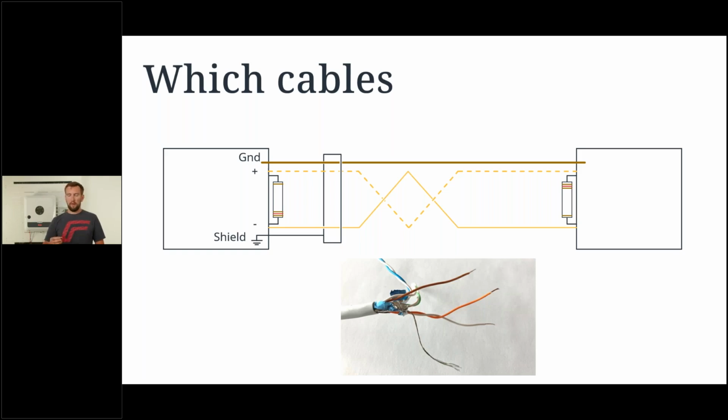We also have a contact for the shield here. This cable has a wire incorporated so we can attach the shield. If that were not the case, then we could always create a contact. We could twist the foil and put a ferrule on it, for example, and connect that then to our shield contact. Or here we can use this contacting wire, wrap it on the shield, and then connect that to our shield contact.